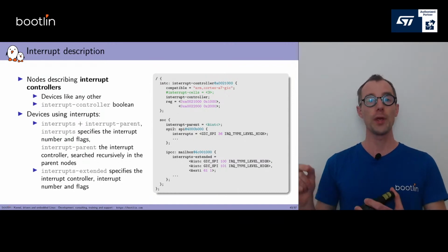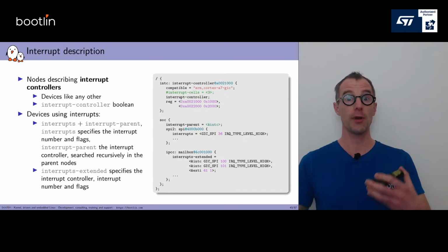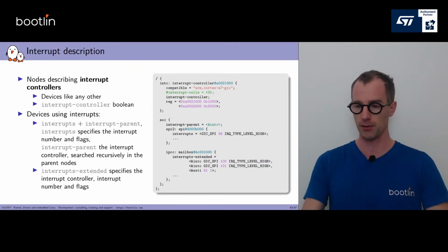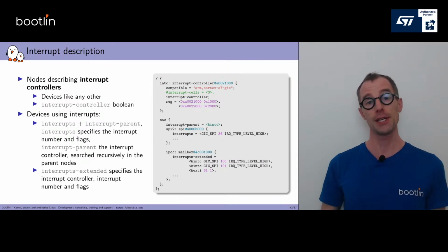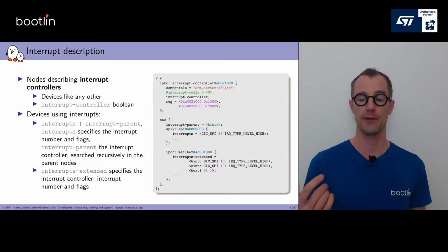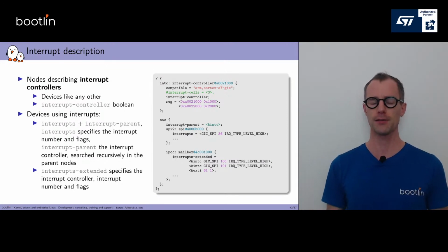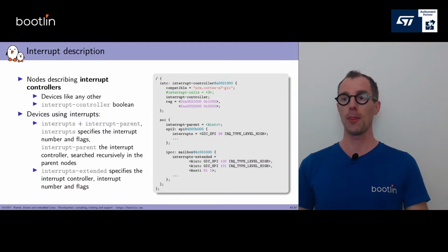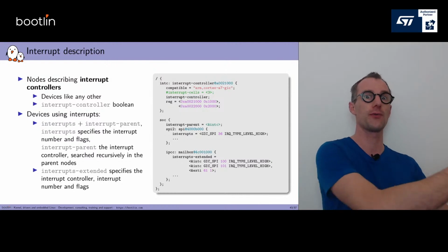And look, we have a third interrupt that comes from a different interrupt controller. So the xi node is not in my example because I couldn't make it fit on the slide, but it's another interrupt controller available on this platform. All right, so that's the two ways of describing how a particular piece of hardware uses interrupts from an interrupt controller.